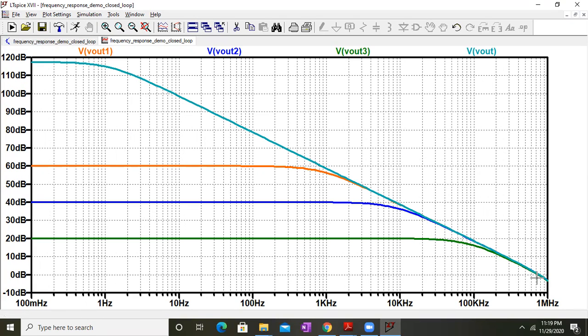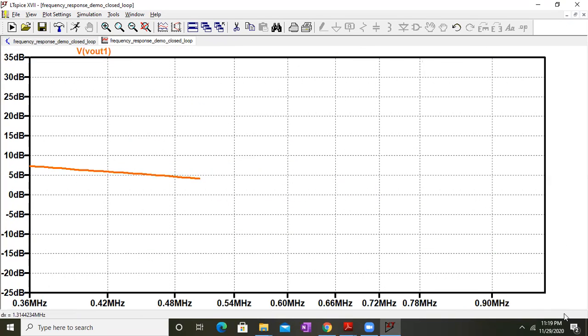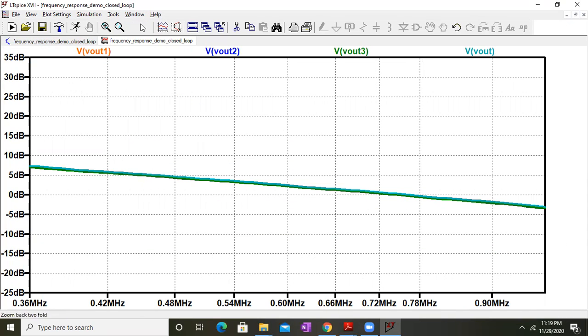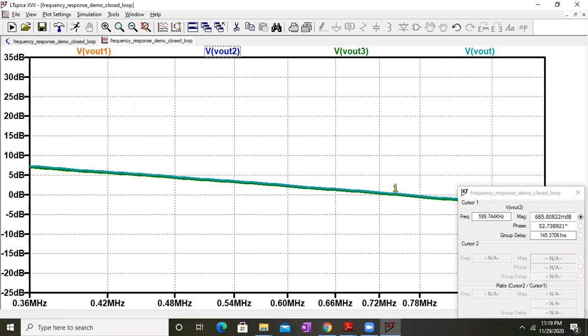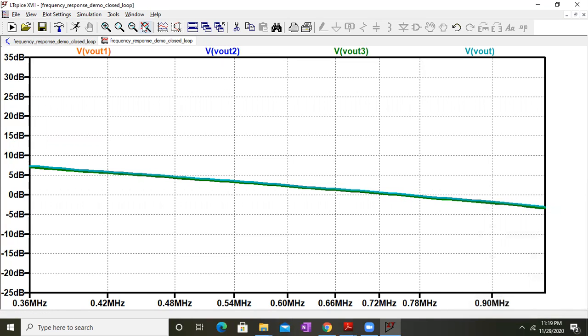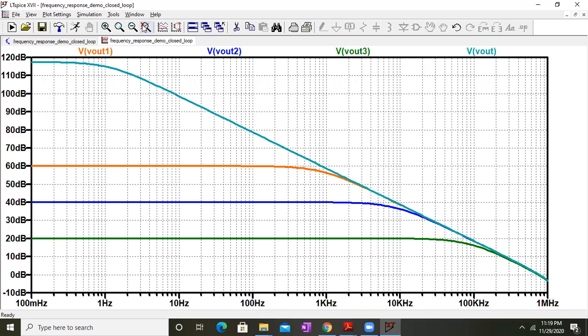the gain bandwidth product is not 1 megahertz. Let us try to find out how much it is, and then we can get an idea what was actually going on. So around 0 dB, let us check around 0 dB. Okay, so we are checking the gain bandwidth product of OP07. It's very delicate, around 760 kilohertz. So around 760 kilohertz is the gain bandwidth product, definitely.